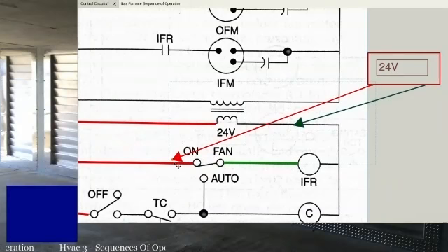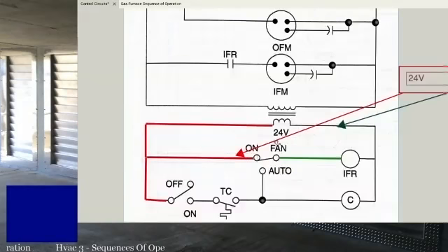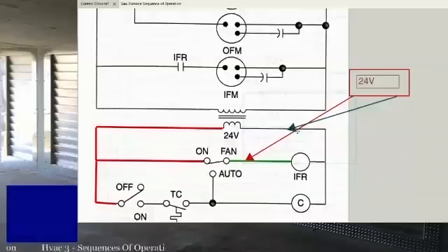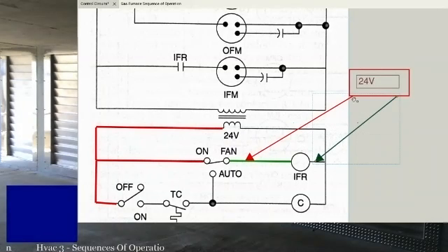And then you go to the other side of your thermostat. Go to the other side of your thermostat and test here on your green wire, and if you're passing power, you'll still get 24 volts. So you know that that fan relay should be powered if you're good on ground. And then if for some reason you're still having an issue, you can move this over to the common side of your relay and check you got 24 volts across it.